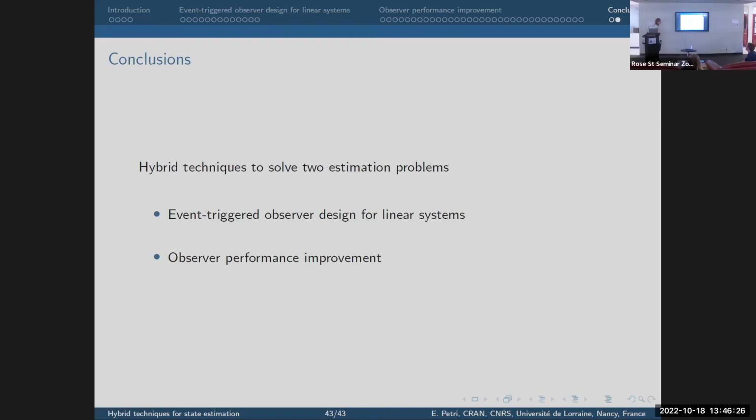In this case, this is not a really good idea because we don't require any convergent property of the estimation error for the additional modes. So we can maybe have one of them that is diverging. If we average them, maybe this is really far away, and we have worse performance. To average, maybe we should require convergent properties also on the additional modes, but to guarantee an ISS property is typically really conservative, so it does not really help to improve. Well, if we take only one of them, we are sure, thanks to the eta, that they are good.